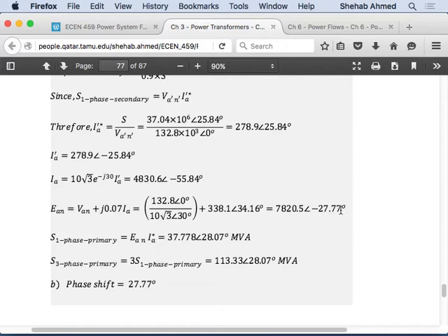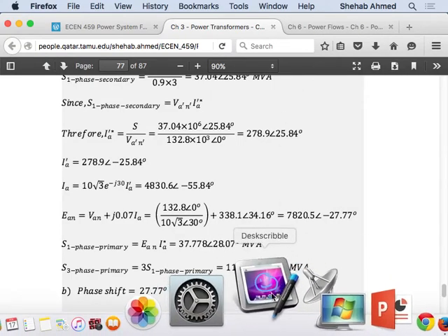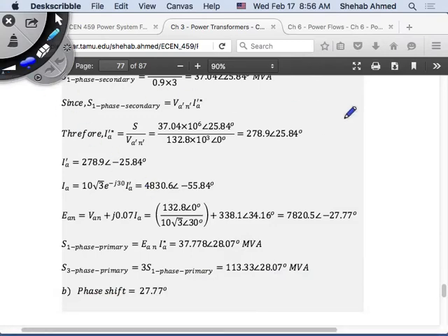Yes, ma'am. I'm just double checking. What you have to substitute in the equation, N primary over N secondary, is the physical turns ratio. Whenever you go back to your equation, this is the physical turns ratio. It is not the terminal voltages, unless I'm talking about a star star or a delta delta.